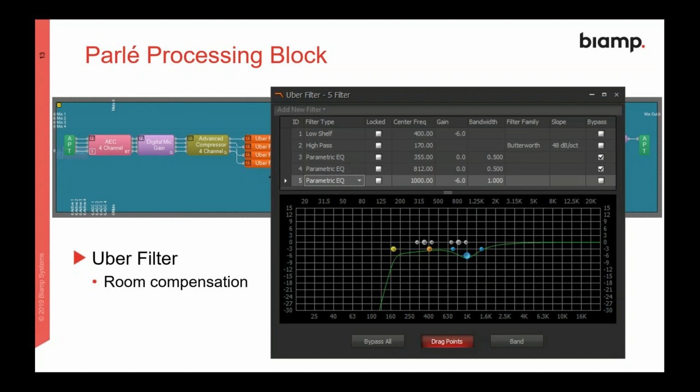Well, the same really holds true for a microphone array as well. They get more omnidirectional as you get lower in frequency, and most of the noise in a room is low frequency noise. So what we find is that we need to roll off the low end. I like to tell people frequently that when you're tuning a room, you really need to roll the low end off more than you probably are comfortable with doing, because visually it looks like you're taking out a lot of stuff here. But in reality, you're not taking out anything important. You're not taking out anything in the speech band.